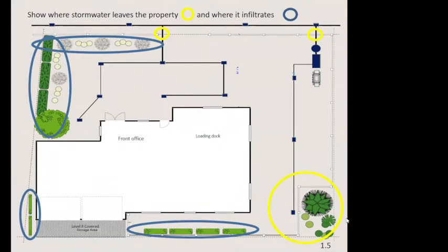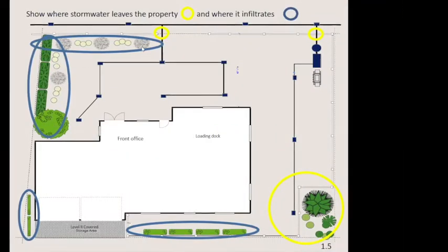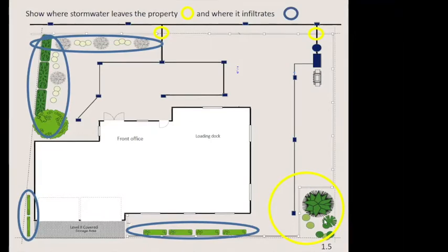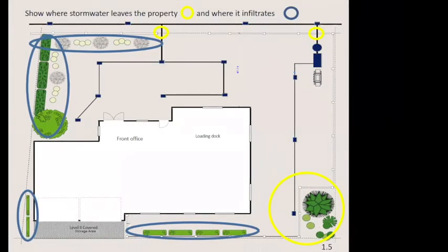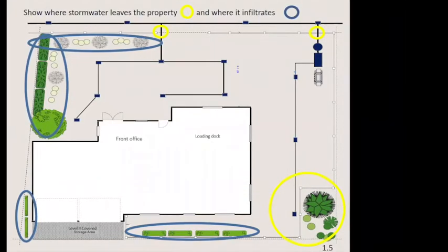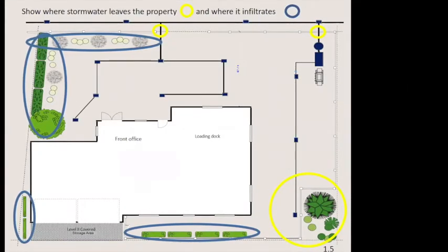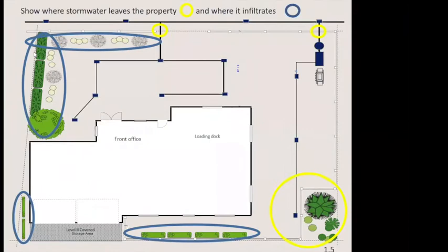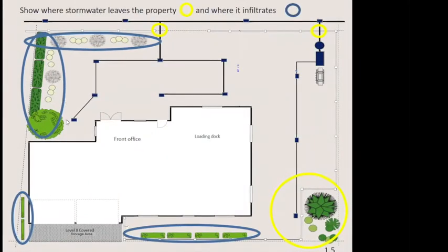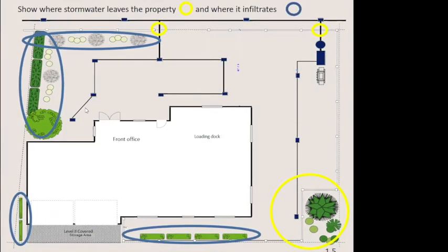It is more likely to end up in the water over here. And in here, it's going to be soil that will absorb it. So if there's a direct connection from groundwater to the local water body, which is a wetland on that side over here, that would be of concern, and it would be leaving your property as well. If these places would absorb water, and you've also got some storm drains pretty close by that would take a lot of that off, then there's not as big an issue.